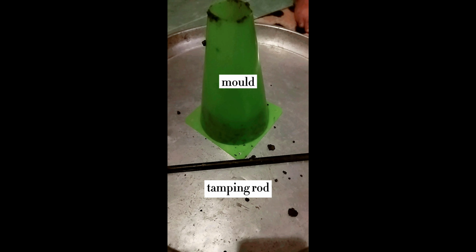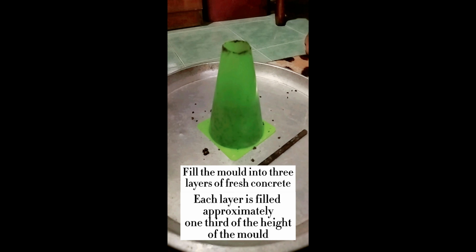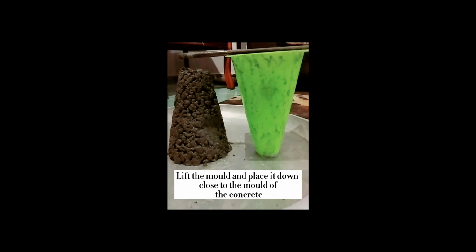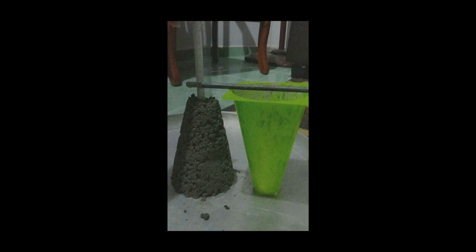Then I set up the apparatus and proceeded with this experiment by filling the mold with the fresh concrete in 3 equal layers, each layer approximately 1/3 of the height of the mold. Each layer is tamped 25 times with a tamping rod. After the top layer has been tamped, I carefully lift the mold and place it down close to the concrete. Then I rest the rod across the top of the inverted empty mold so that it extends over the concrete. I measure the slump of the concrete using a ruler and record the measurement. From the observation, the type of slump that I get is true slump.